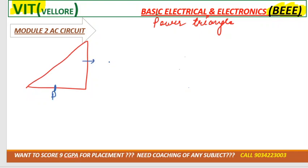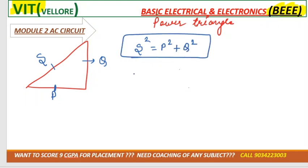That is reactive power, and the combination is known as apparent power. Understood? So we'll have S square is equal to P square plus Q square, right? And can you tell me what is cos phi in this case?